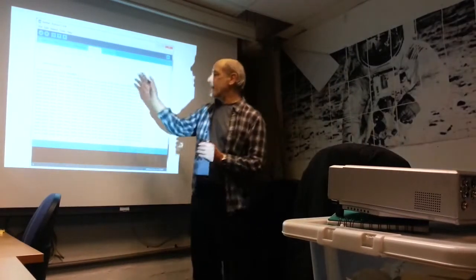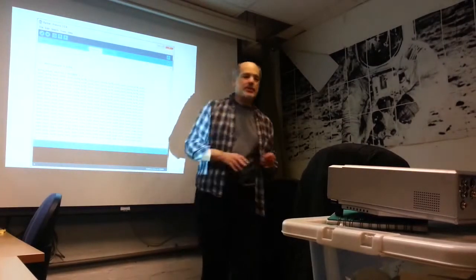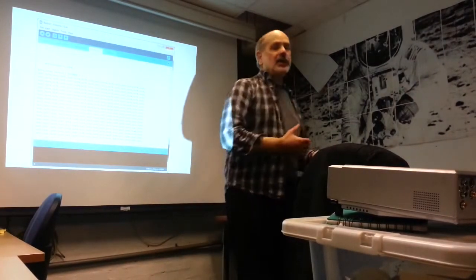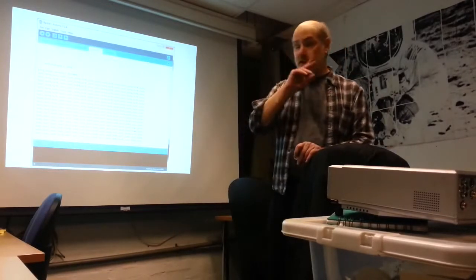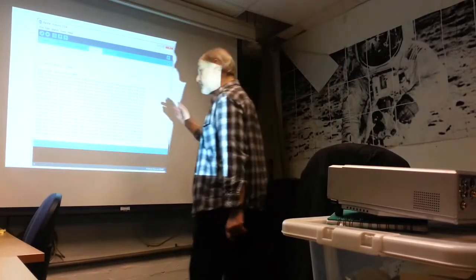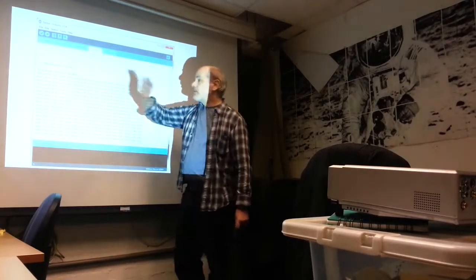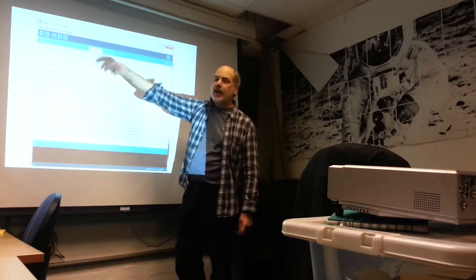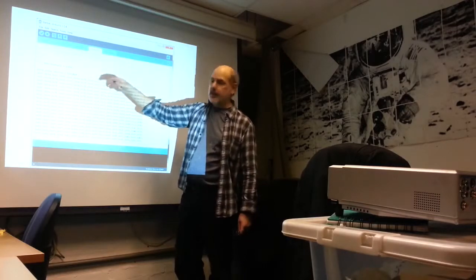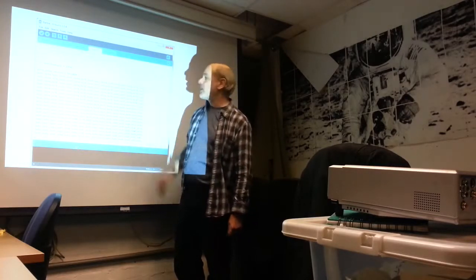The last stage of the build process is to produce what's called a hex file. It's a kind of industry standard format. It was initially developed by Intel for the very first microprocessors, and it's still used. That format defines the ASCII values in hexadecimal of all of the bytes of the program.